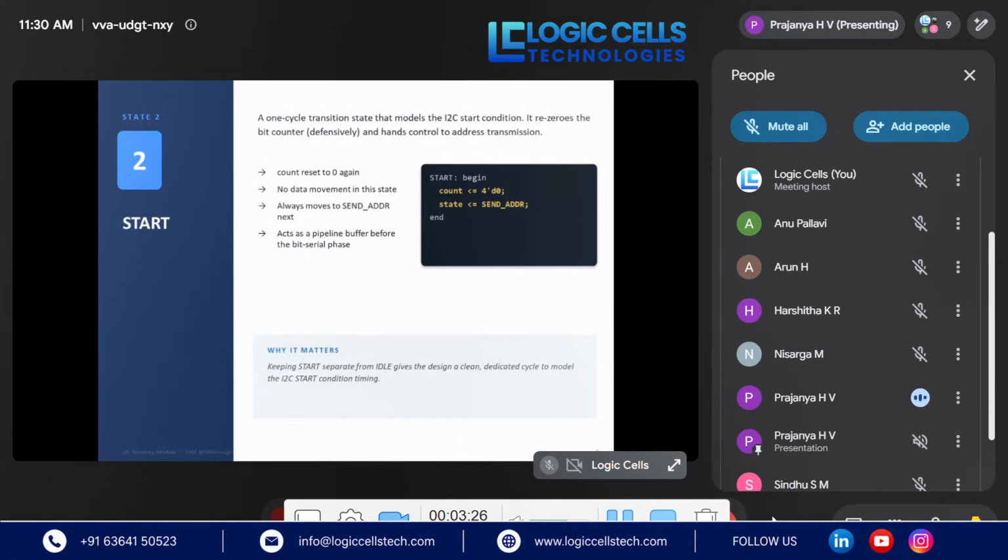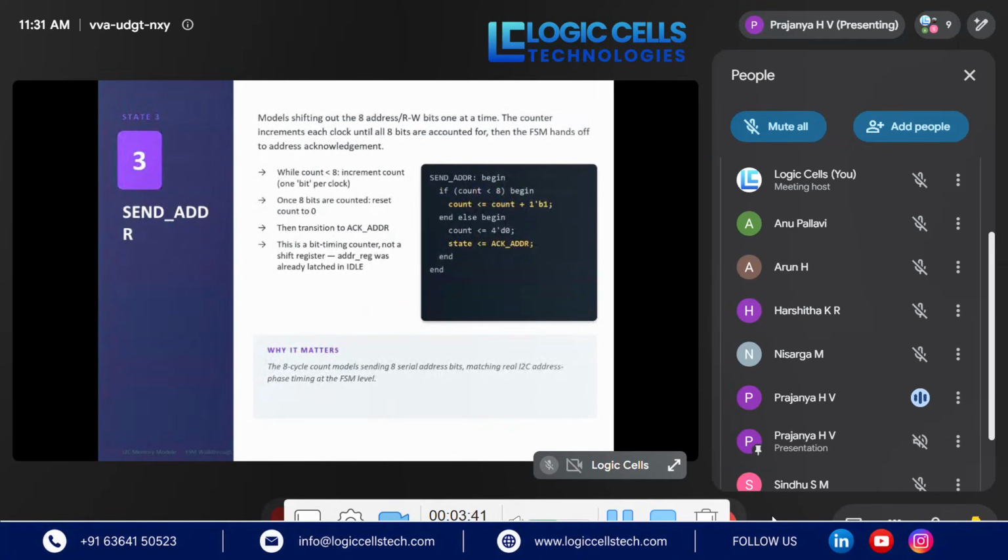where in the start state SDA is reset to 0 and SCL remains 1. Next it moves to the send address state. The module shifts the 8-bit address and read or write bit, 1 bit at a time.